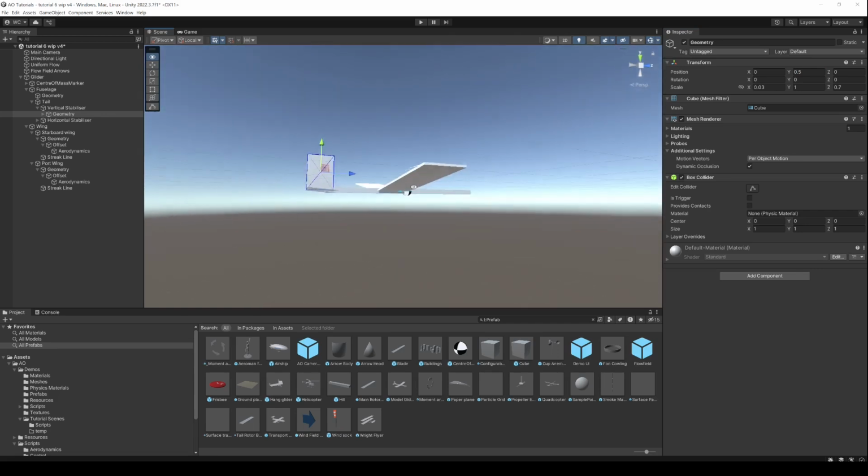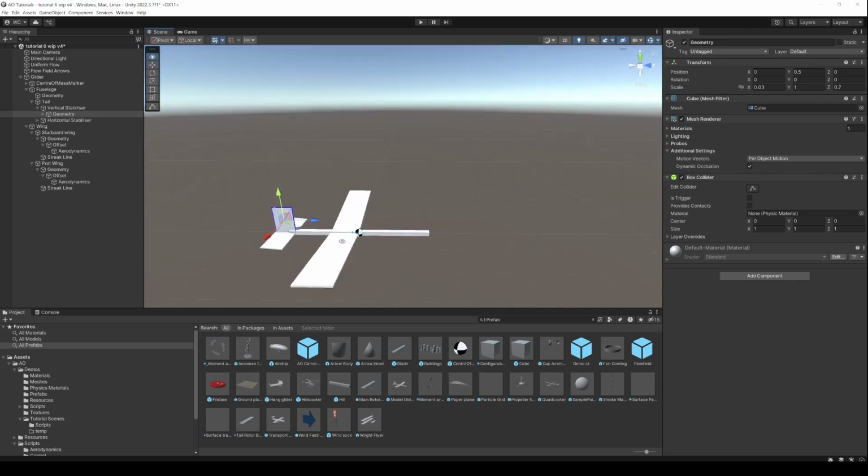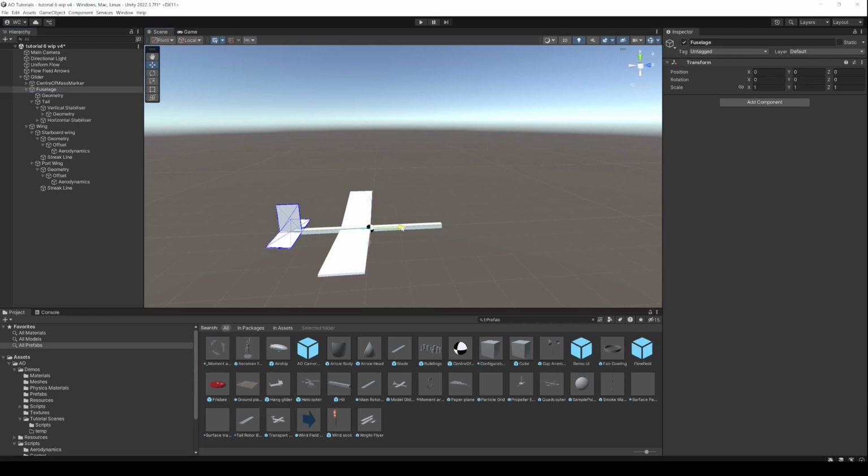fin. Next up, the tail looks a bit too close to the wing, so let's sort that out. So if we grab the fuselage, we could just move it to wherever we wanted on here. That's a good position. I'm going to move it so it's around there, and in fact let's put it exactly as -0.6 back, so it's 0.6 meters back from the leading edge.